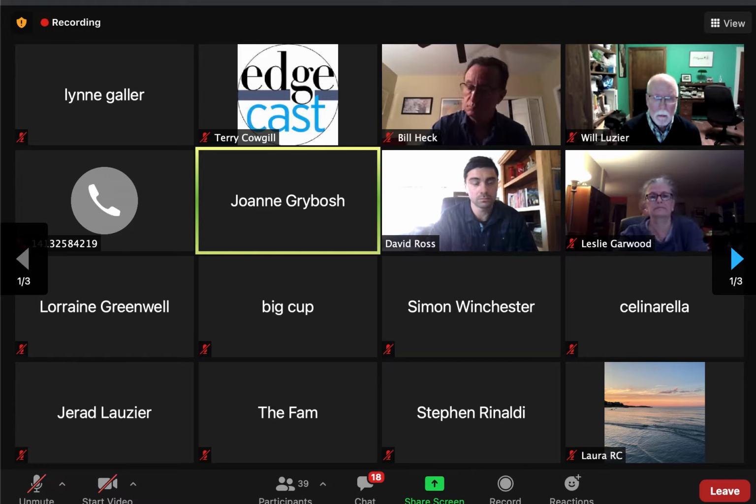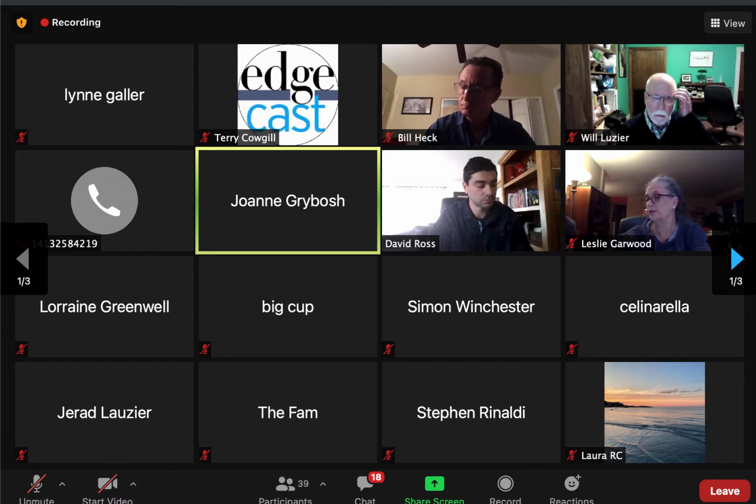A good question. I can put that in perspective for you. When I started, a 100-year rainstorm was 6.4 inches of rain in 24 hours. If you think of that in snow in Massachusetts, it's a factor of 10, so that'd be 64 inches of snow. This design is based on an online source now because the climate change is very fluid. We're at 8.17 inches now, which is what this is designed for the 100-year storm. So I designed it for the 2, 10, 25, and 100-year storms. That way it balances.